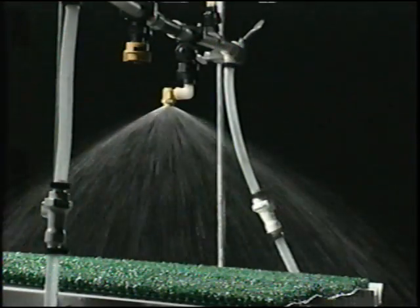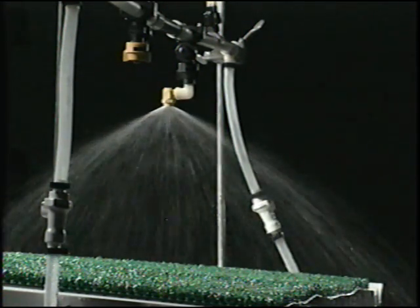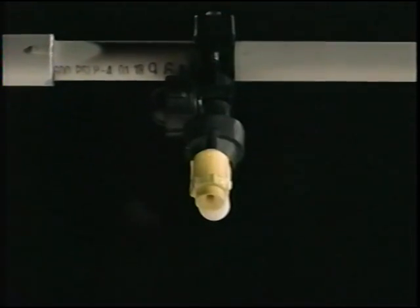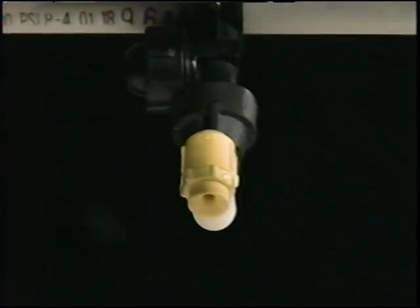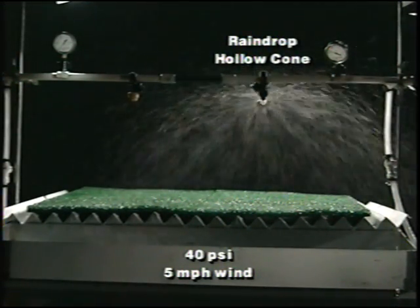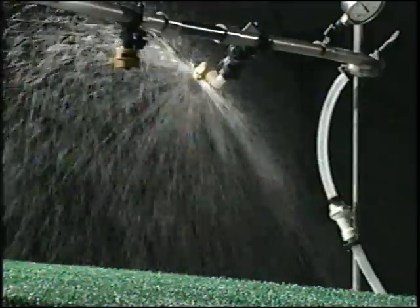Additionally, the performance of more conventional nozzles can sometimes be dramatically improved by merely adjusting the angle of orientation. Here we see a raindrop hollow cone nozzle, which features a secondary swirl chamber at its tip that reduces pressure and creates larger droplets. However, this design is more susceptible to side wind drift, moving the spray pattern off the end of the boom, because it must be operated at a 30 to 45 degree angle to achieve pattern uniformity.